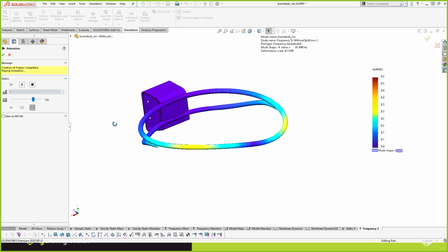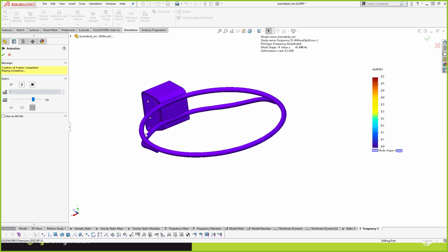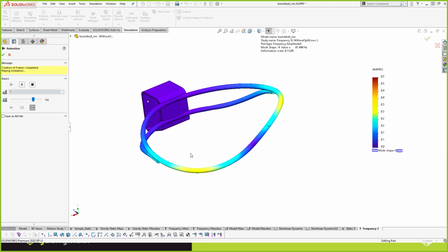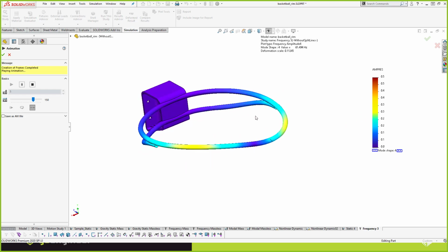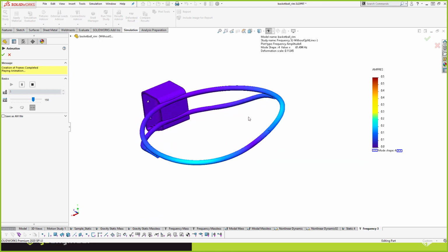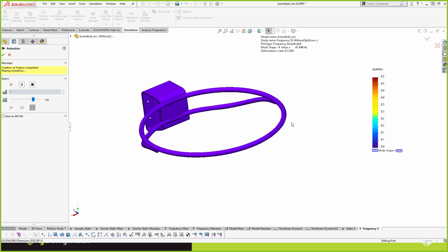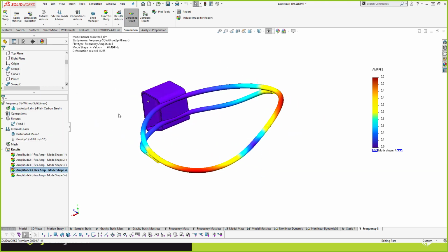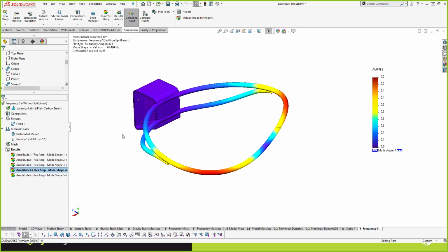This is like a twisting mode. This one would come into play if I hadn't been hanging right in the center. If I had been offset a little bit to the right or left, then I'd have to use, picture doing that modal superposition, I'd have to add quite a bit of this mode to get to the right answer. Okay, mode 4 would be pretty important. So it looks like mode 1 and possibly mode 4 are two very key ones here.